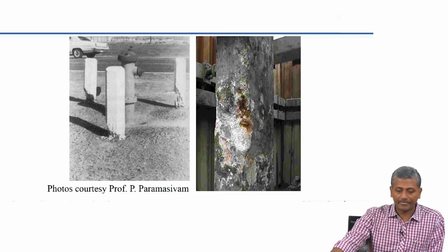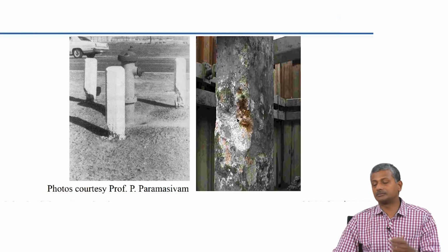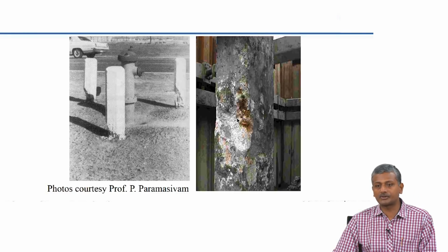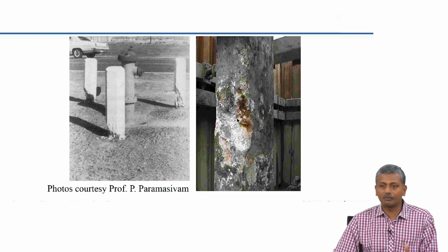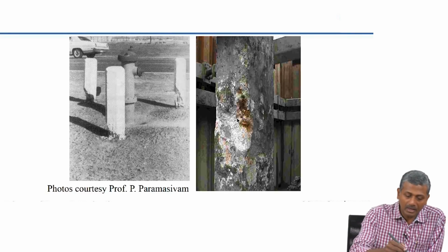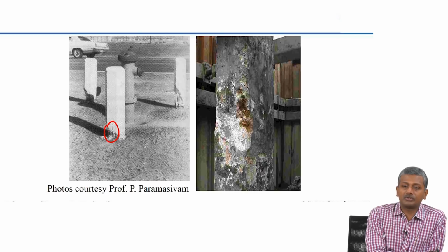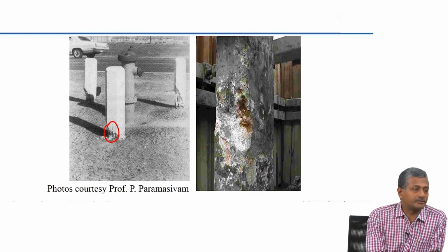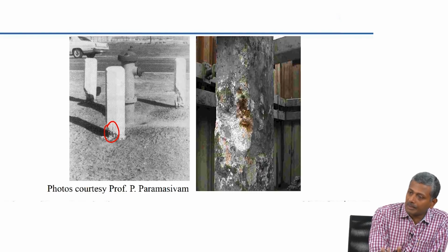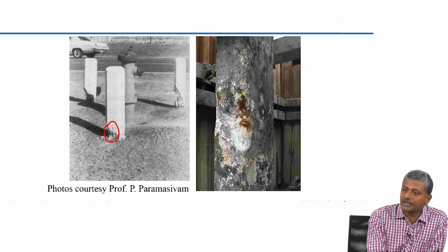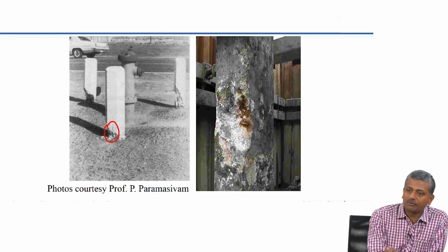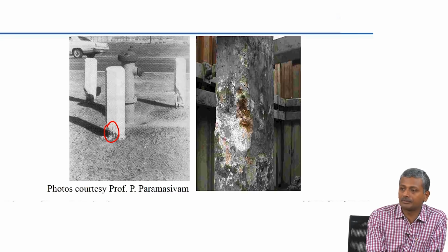you have a loss of strength and integrity of the system. So, this is a picture from a column exposed to a sulfate soil, and this is exactly what we were talking about in the last class, where you have the major part of the damage at the soil air interface, and that is because not only do you have a chemical effect here, you also have the wick action, sorption, all of which form a large part of what is happening to this system.